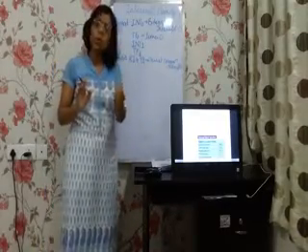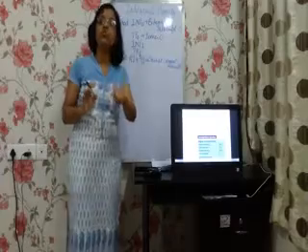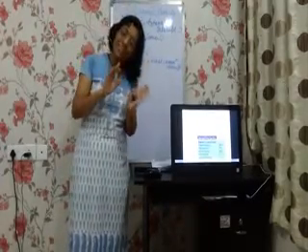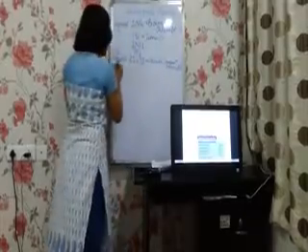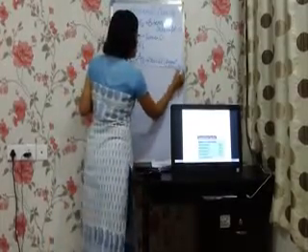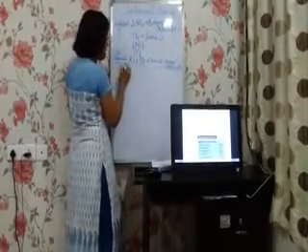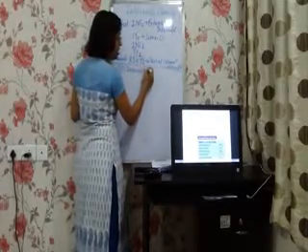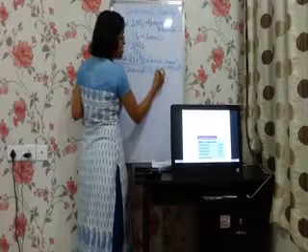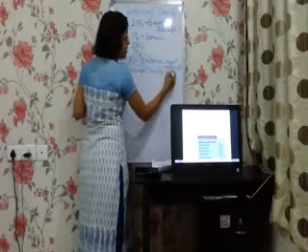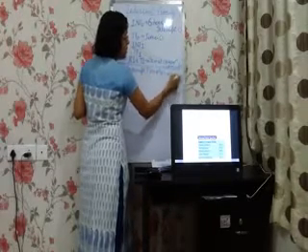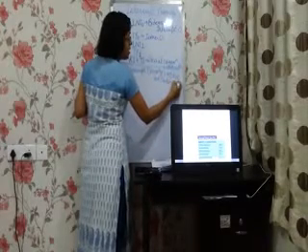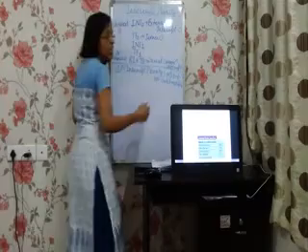Now, if the programmer wants to alter this priority, the programmer can do so by configuring a register called the interrupt priority register. So we have a special function register called the IP register, which is an 8-bit bit addressable register. The programmer can assign priority on their own basis.